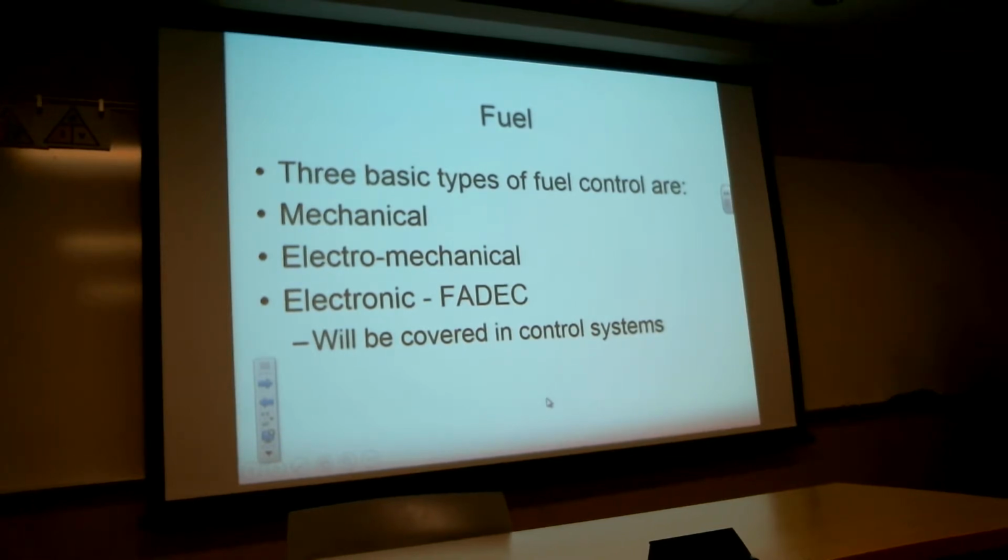Gets rid of all those problems. So you have to trim an engine after you change the fuel control with a FADEC? No. All you do is a leak check. And that's just to make sure that anything that you put on seal-wise isn't going to leak and you're not going to have a fire on your hands. Because the FADEC will self-trim the system on the engine. It's taking a lot of sensing information off of the aircraft and is feeding it all into the computer.